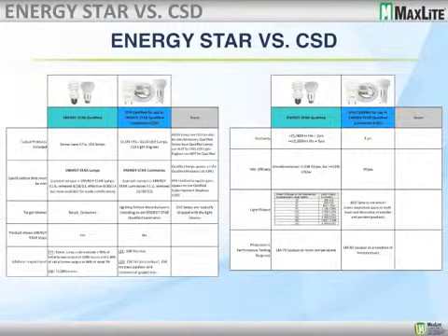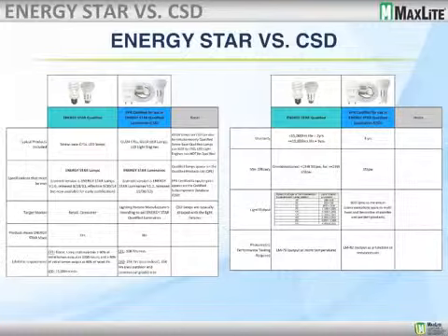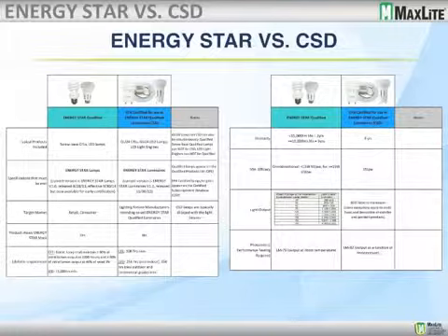If it's just the light engine itself, a GU24-based LED lamp or a GU24-based CFL, or a light engine where you have maybe a puck style or some other physical shape along with its driver set. So this is not a finished product one can use in their home, but it's a component for a fixture that they can use in their home. So that's one major difference.